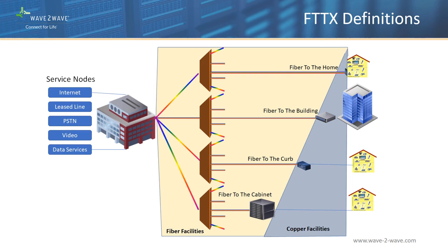However, considering take rates, spare fibers, splitter usage, future service offerings, distance from CO, and other unknowns, the number of fibers in the outside plant cable would more likely end up being closer to 1 per 8 homes, or 400 fibers. FTTB typically uses the point-to-point architecture in the outside plant, providing a dedicated fiber to each building or block of buildings. In fact, the percentage of commercial buildings connected to a fiber optic network in the U.S. reached 49.6% in 2016, according to the Vertical Systems Group.